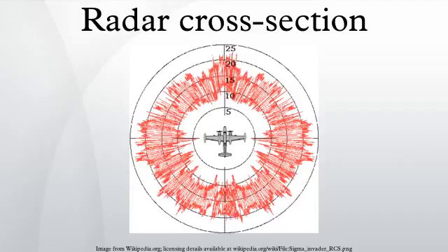Materials such as metal are strongly radar reflective and tend to produce strong signals. Wood and cloth or plastic and fiberglass are less reflective or indeed transparent to radar, making them suitable for radomes. Even a very thin layer of metal can make an object strongly radar reflective. Chaff is often made from metallized plastic or glass with microscopically thin layers of metal. Also, some devices are designed to be radar active, such as radar antennas, and this will increase RCS.